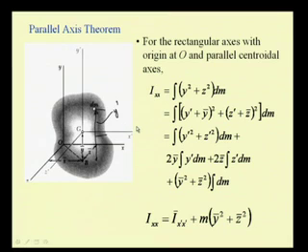So, we write it as I bar. This notation helps us know that this is a second moment of the mass with respect to a centroidal axis. So, this x prime axis is passing through the centroid. So, we have this quantity as I bar x prime plus, what is this quantity? This integral dm is nothing but the mass of the body.